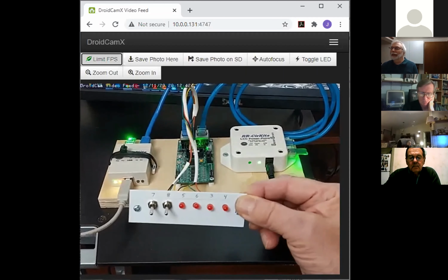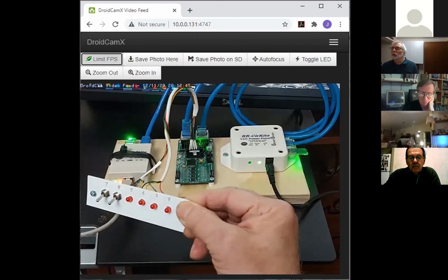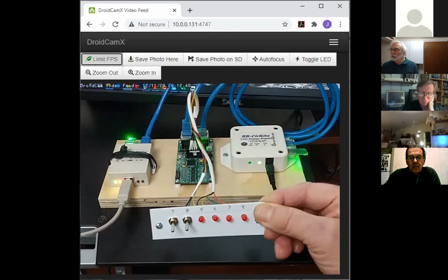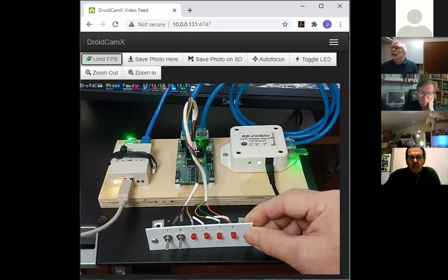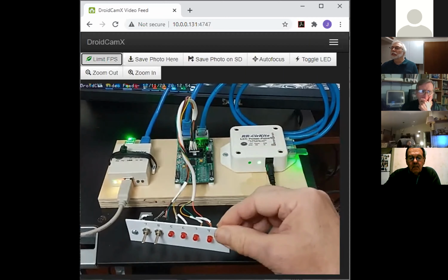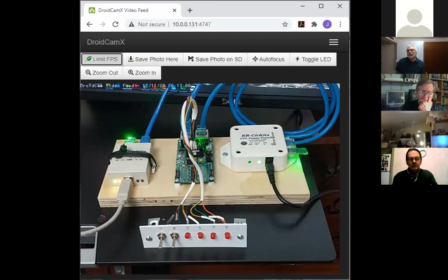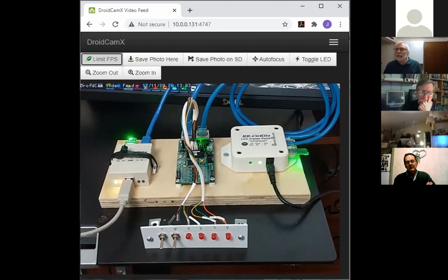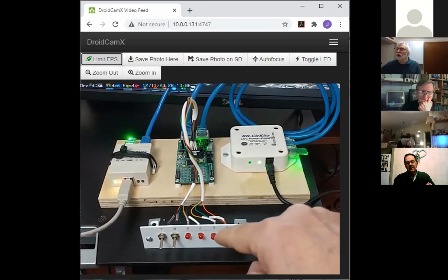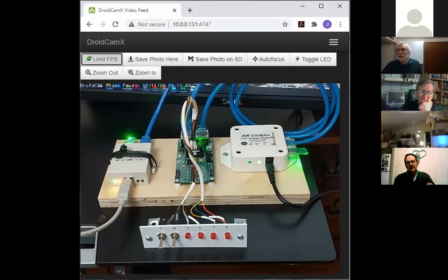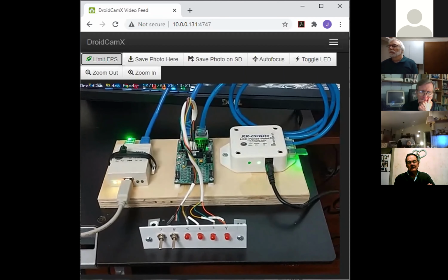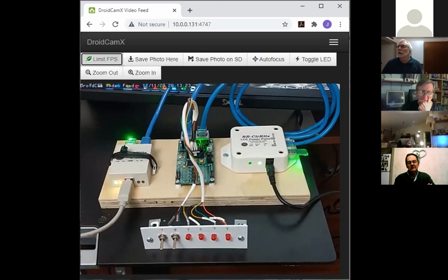And there's my layout. So this guy is playing the role of the entire layout. All I've got is a little board with 2 switches and 4 LEDs on it, and it's hooked into the LCC board over here. And so I'm going to program this thing to do a few things. It's just switches and lights, but you do exactly the same things. If you can understand how to make some lights go off and on when you flick some switches, you've got it. You know how to use this thing, because controlling a turnout when a block detector goes off is exactly the same as controlling a light when a switch goes off. The events don't care. It's exactly the same. So I can use this to show you what's going on.